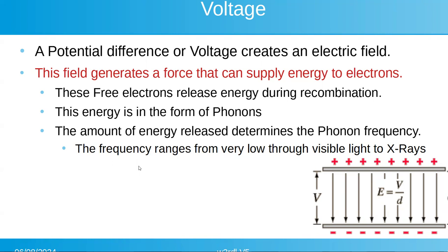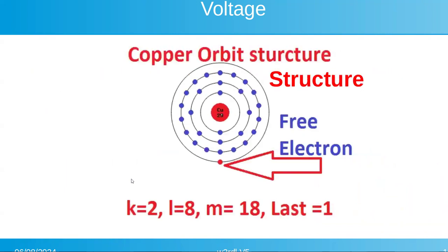And that force that we talked about is providing enough energy to cause an electron to move from the valence shell outside and become what we call a free electron. It has to provide enough energy for that to happen. Once that electron recombines with another atom, possibly the same atom, in order to do that, it has to give off that excess energy, because when it's recombined, it's back to the same energy level that it was in that shell.